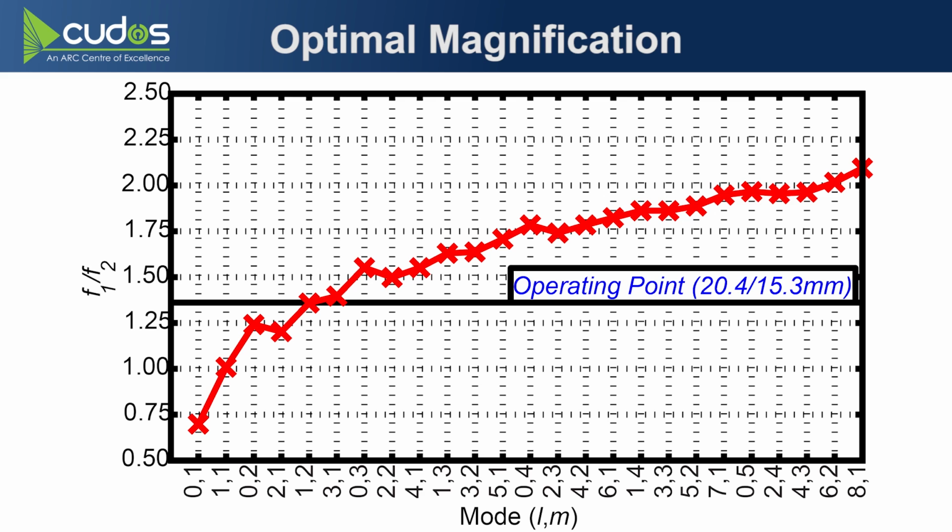But for multi-mode fiber, there's a large spread in numerical apertures for all the different modes. For example, here's the optimal focal length ratios matching an SMF to each mode of a 50 micron core graded index multi-mode fiber. You've got the highest order mode with an optimal magnification of 2, which is basically the ratio of the NA of the SMF, about 0.1, to the NA of the MMF, about 0.2, down to the fundamental mode of the MMF, which actually needs to be scaled to 75% to match the SMF.